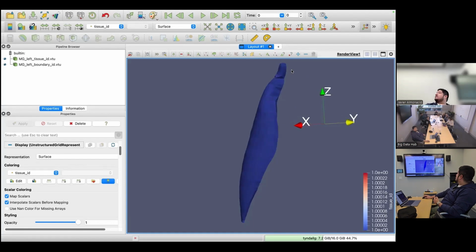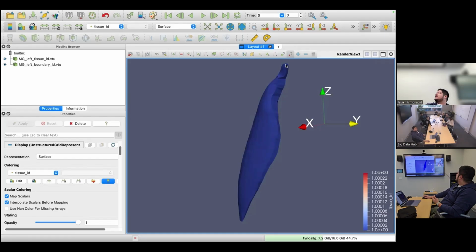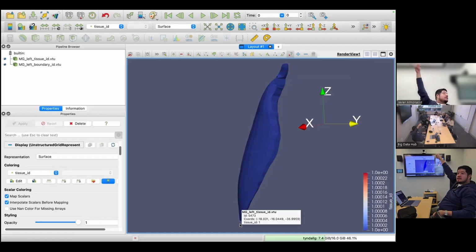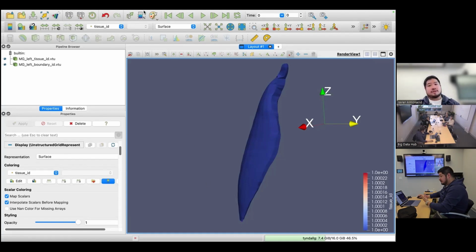So in this case, what I'm doing is to take the 2 furthest points, which I can hand select pretty much. I have a tool here that I can use to visualize point information, like that. I hand select them, and then I take the vector. The difference between those 2 points will give me a vector, which is what I consider my line of action. And then I'm going to align that line of action with the x-axis. So I need to rotate that vector, and with that, I will rotate my entire mesh. And that's what the preprocessor tool does.